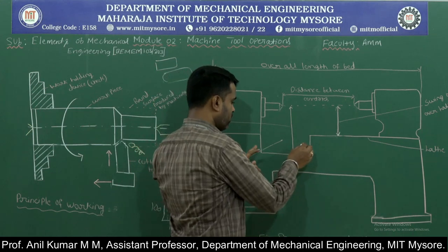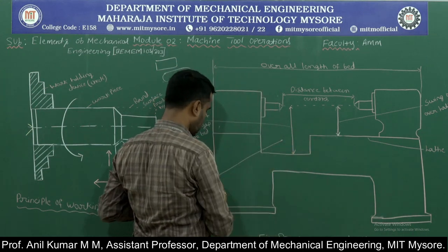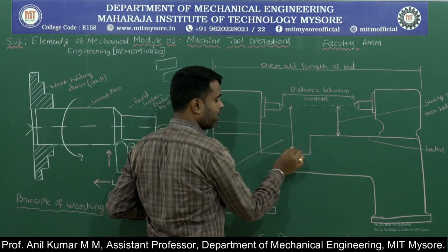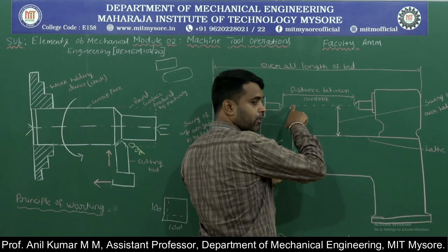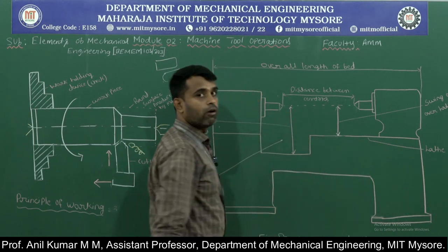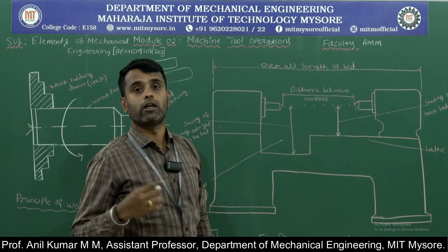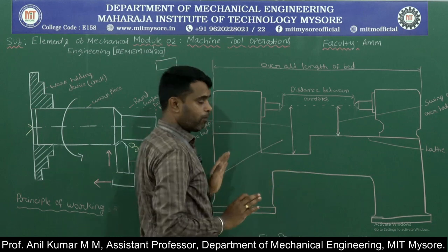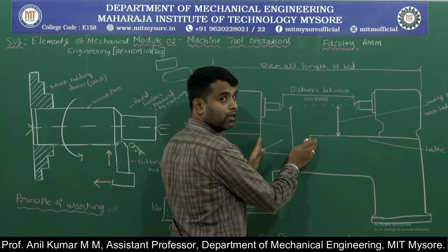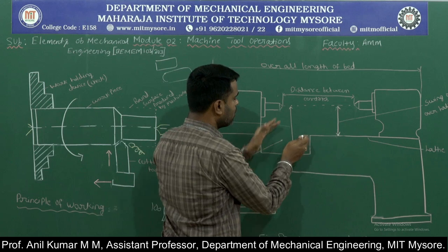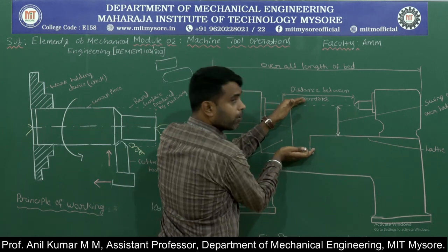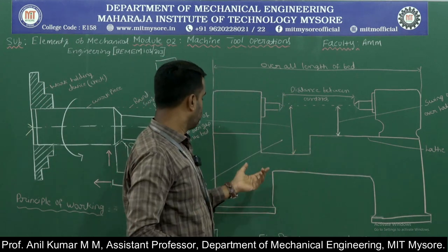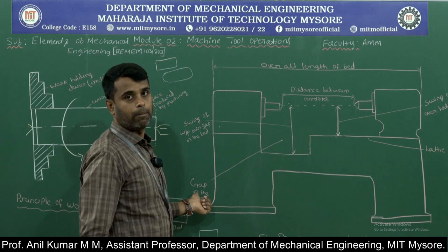And next, if there is any gap in the lathe bed, then in that gap the maximum diameter and the maximum width of the workpiece that can be revolved or rotated is specified. That applies when the lathe bed has a gap.